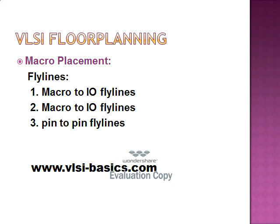Macro to macro flylines are used to get an idea of which macros should be placed closer to each other, and macro to IO flylines give an idea of which macro has to be placed nearer to the IOs, that is, the chip boundary. And pin to pin flylines are used for the orientation of the macros.